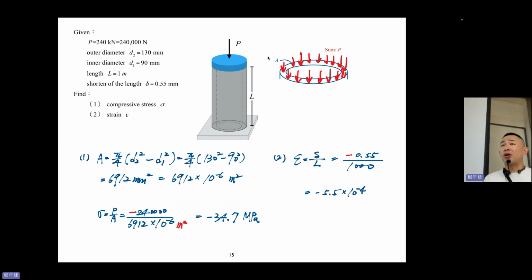If you calculate a strain like 12%, something is wrong. Of course, there are still some materials which can have such high strain, 12%, 18%, and still go back to their original shape. It is called superelasticity.